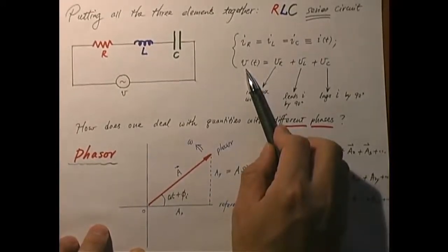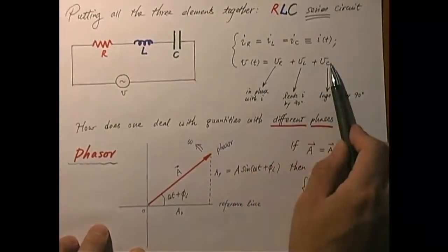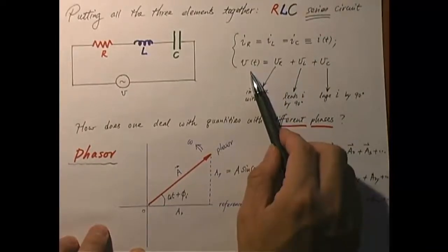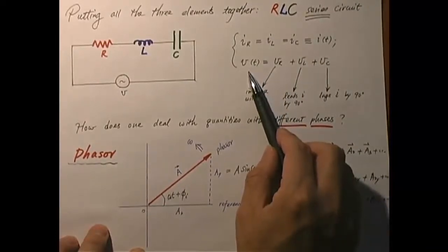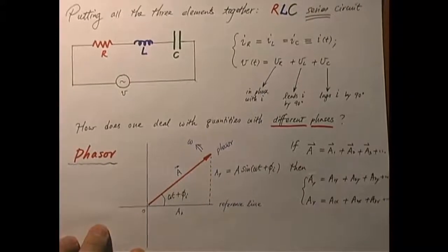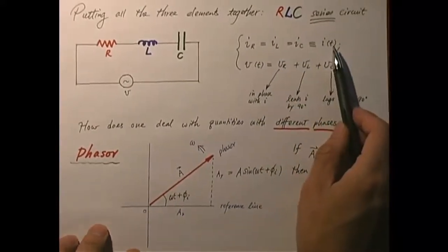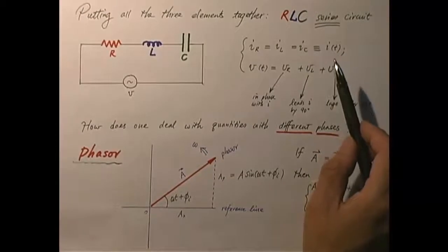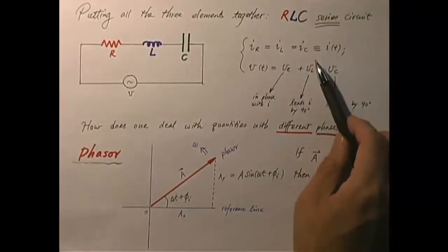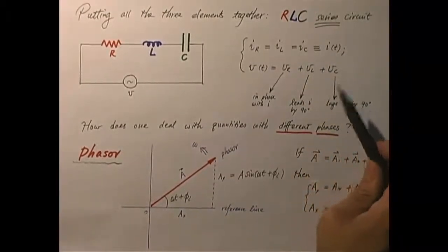This is the sum of all these y components, and it is also equal to the y component of the resultant vector. See that? So the idea is I'm going to define a phasor, which is a vector, in association with each of these real quantities, which of course are not vectors, they're scalars, such that each of these quantities is the y component of such a phasor.